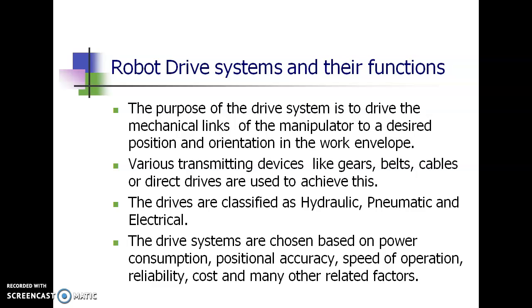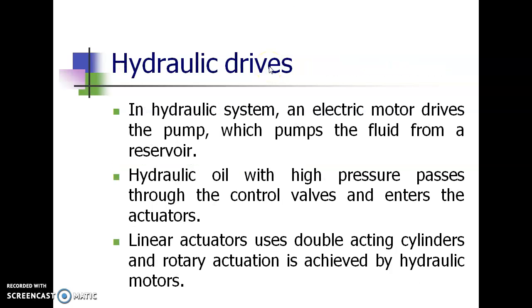So the drives are classified as hydraulic drives, pneumatic drives and electrical drives. The drives are chosen based on various factors such as power consumption, the positional accuracy required, speed of operation, reliability, cost and many other related factors. First, we are going to discuss the hydraulic drives.